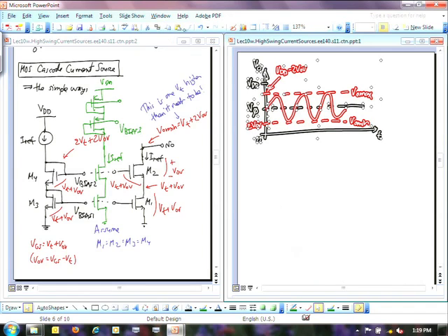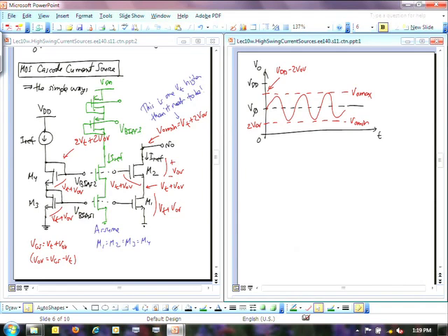Let me just kind of steal that. Now, what am I looking at? Now I'm no longer looking at something as simple as this. Okay, instead of this being V out max and V out min, now I got to add a VT to this. Okay, and so there's 2 V overages there plus a VT. So maybe that's what that is there. That becomes VDD minus 2 V overages minus a VT. This now becomes VT plus 2 VOVs.